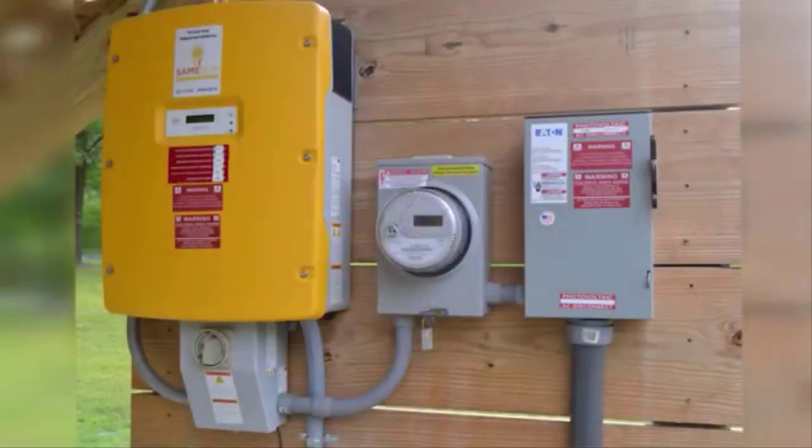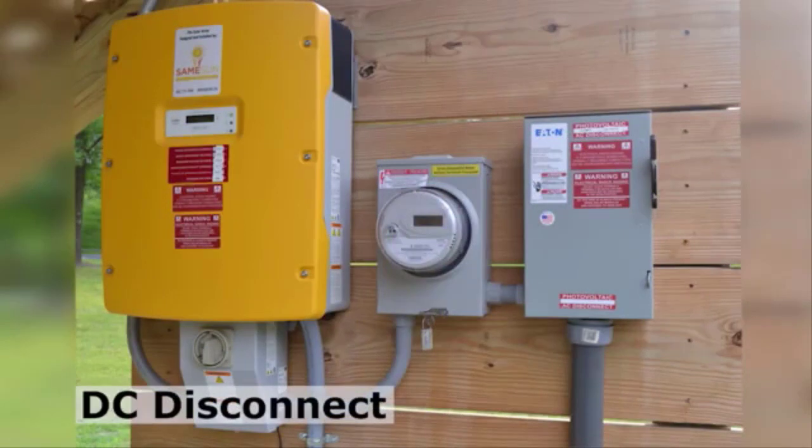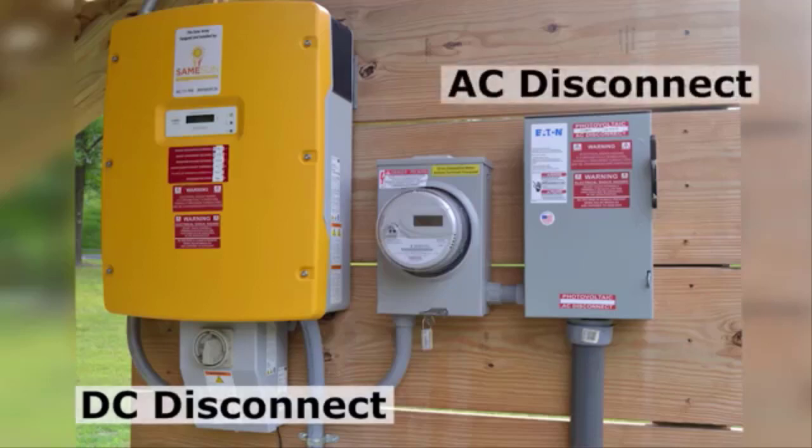According to the NEC, one requirement is that there are disconnects placed between the DC side of the photovoltaic system and the inverter, as well as a disconnect on the AC side of the system. That shutoff is typically part of the inverter itself. Electrical connections may use USE-2 for outdoor use or PV photovoltaic wire for outdoor and sunlight ratings. These are defined within the NEC in the same way that typical indoor and outdoor wiring is already defined.